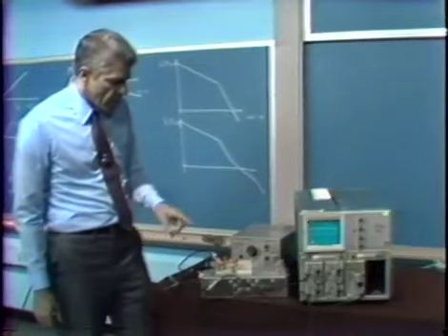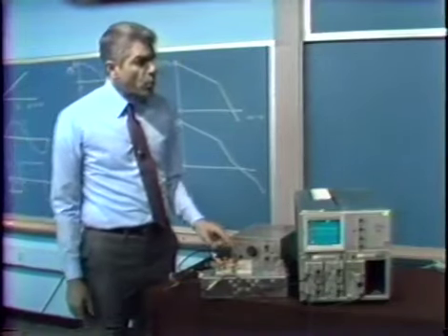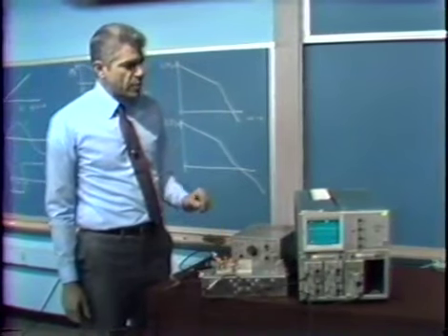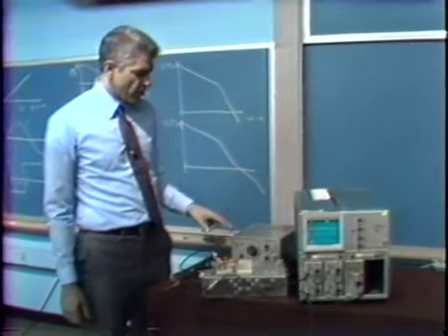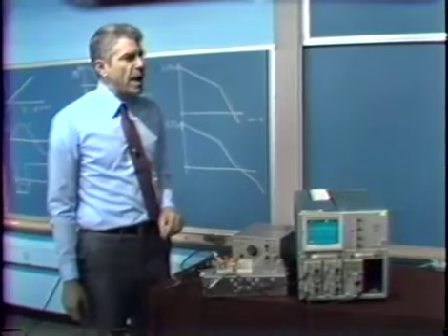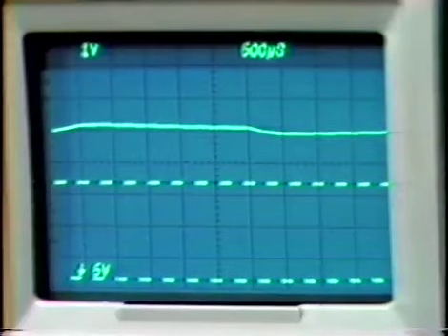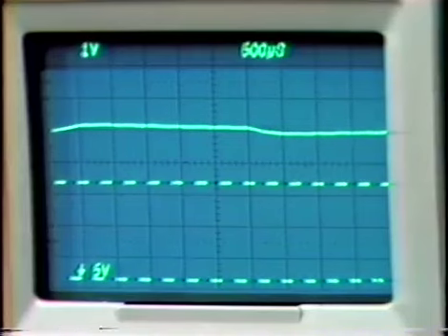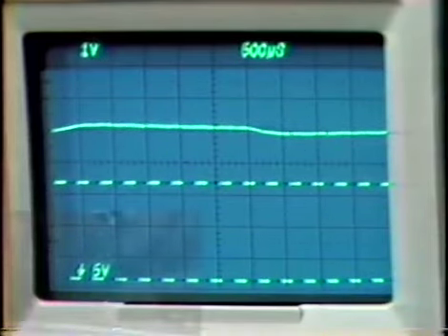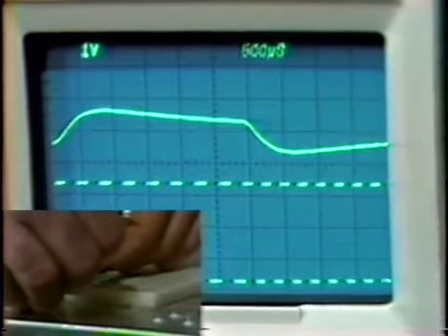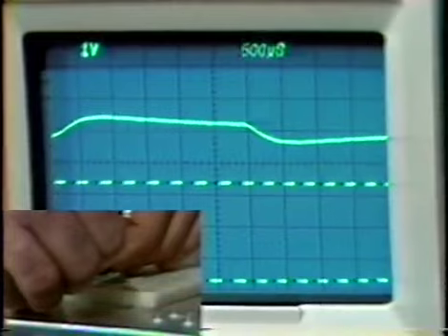What we're looking at is, on one hand, the signal that's applied to the VCO, which is proportional to the command signal. The bottom trace is not the actual operating frequency of the loop, but a divided multiple of the output frequency at which the phase-locked loop is operating, so we can see it conveniently on the same sort of time scale as the VCO signal. And what we can observe here is the behavior if we increase the amplitude of the drive signal.